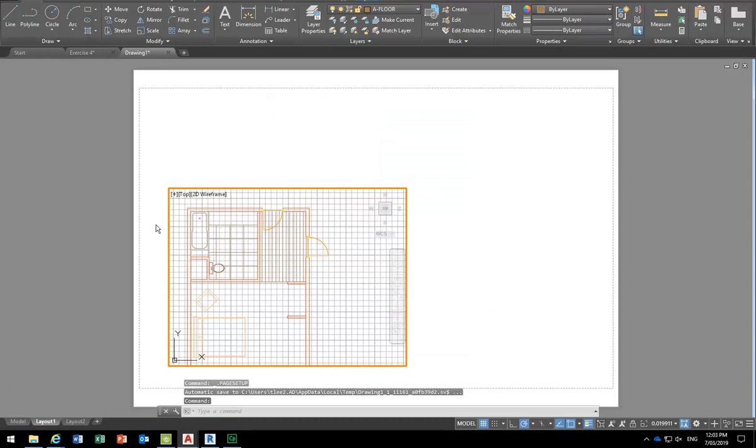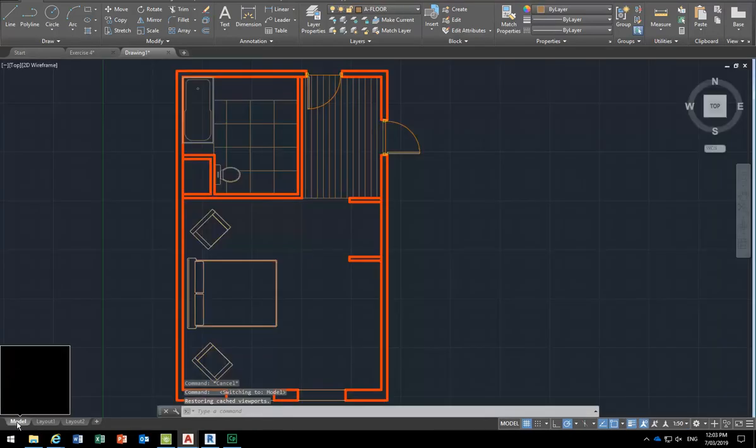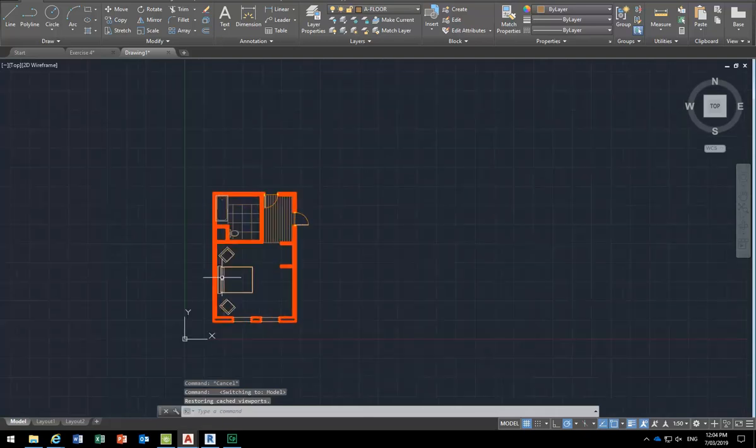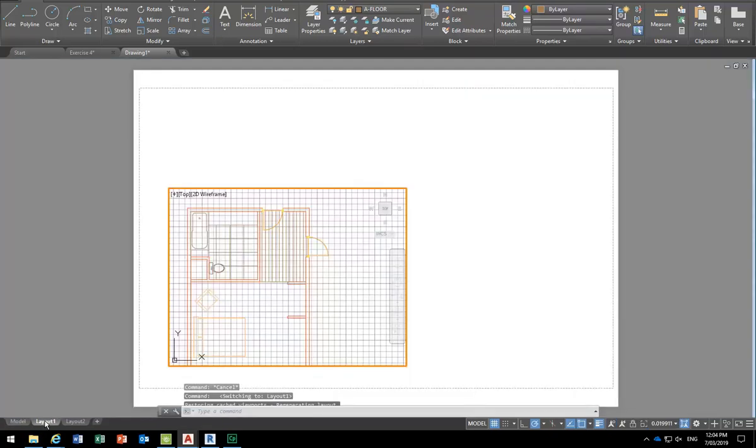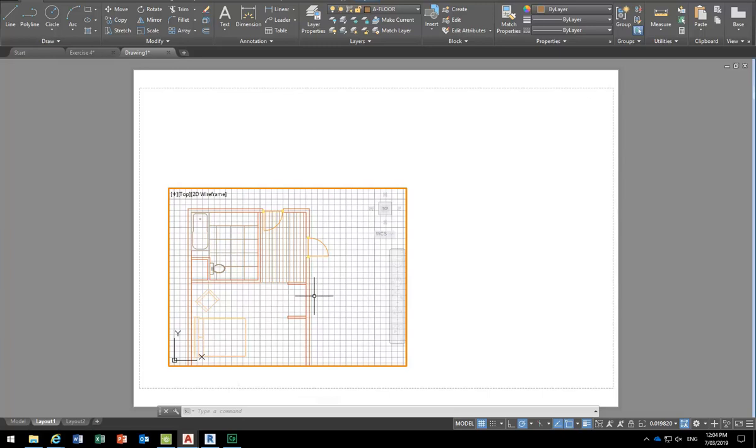And I've got a viewport, so the viewport is the thing that lets us see what we've drawn back on the model tab. So anything you draw there, you can keep switching back to it to see. When you draw things on the model tab, they come up in these things called viewports on your page. So I already had a viewport, and you'll have one too. And does that just save it automatically? Yep. Oh yeah, it's all linked. Yeah. It's all in one file. Oh yeah, that's good to think about that. Yeah, because not all programs are the same.